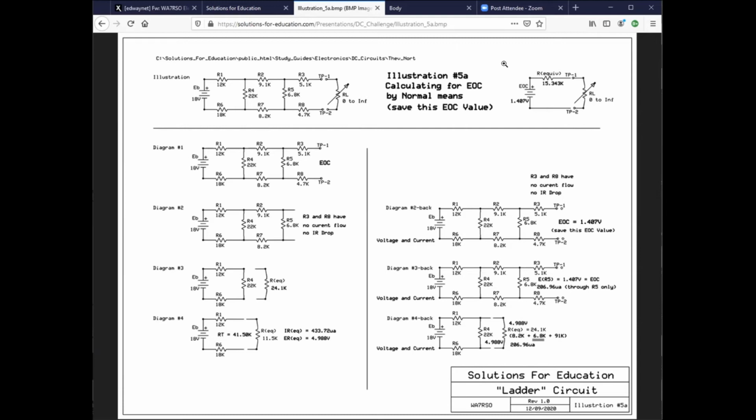That's the one if the president punches in the codes to fire missiles, in retaliation or whatever, then the codes had to go into this one particular box, which had all kinds of security alarms on it. So if somehow signals were trying to come into the box that were not authorized, it would set off alarms like you wouldn't believe. We called it the tickle box. Well, what happened is we found an interesting situation, very frustrating. We found that some of the equipment was sending signals through the ground wires. And we had really good grounds on that setup. And these signals were going into the tickle box and setting off alarms.